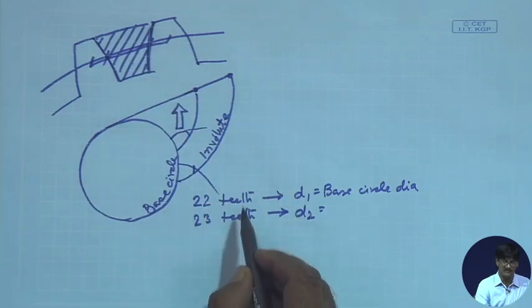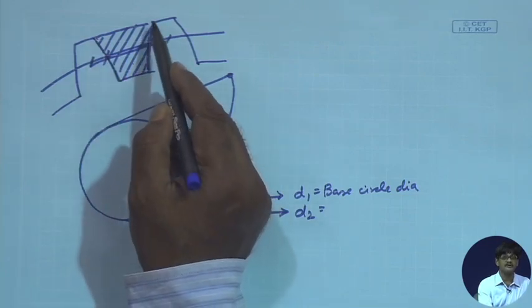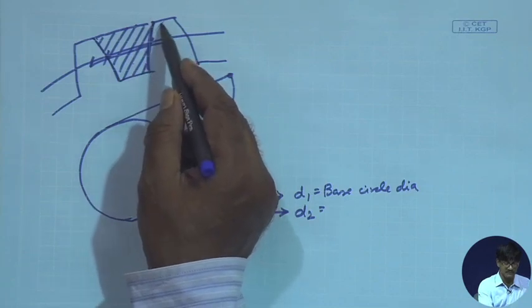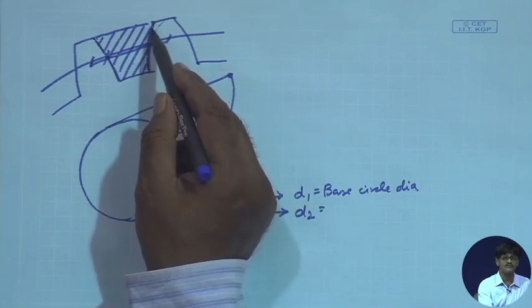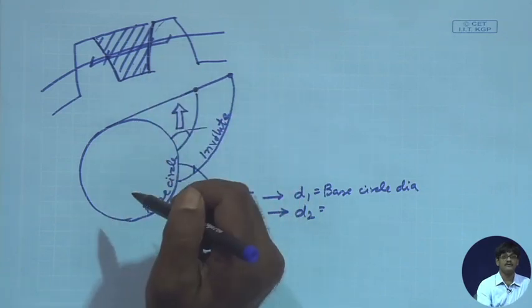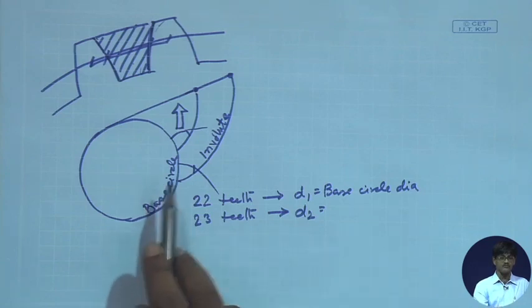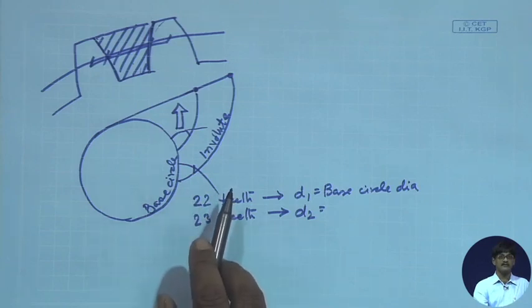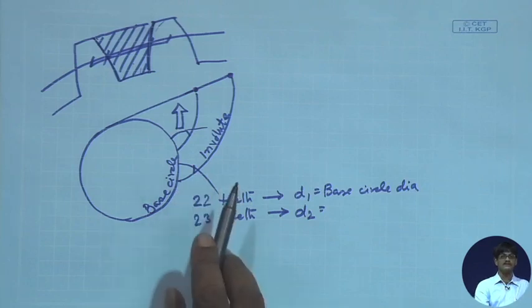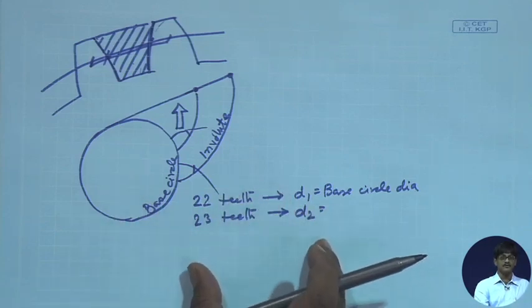For 21 teeth, one cutter, because this particular profile is becoming different. These flanks are either going to be very much curved and slanted, or they are going to become more and more straight. They move towards straight lines as we go for a higher and higher number of teeth, towards the rack. Therefore, this is bad news for milling. You have to spend an immense amount of money to equip yourself with all the cutters required for cutting all the gear teeth included in a particular module.